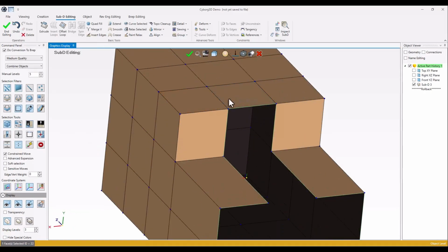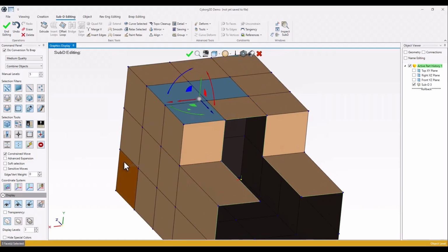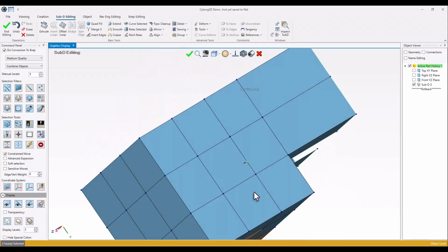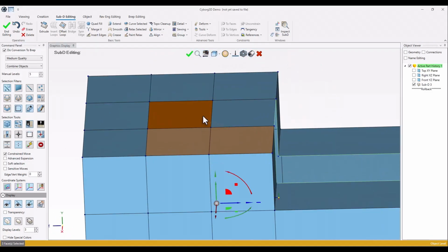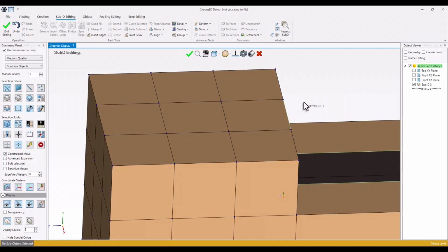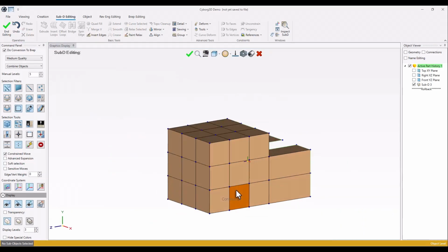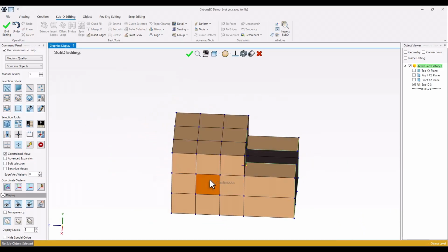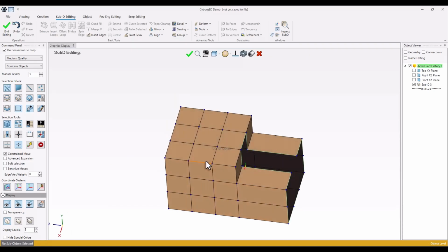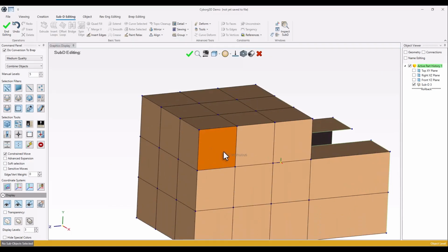And the second thing here is reverse the selection. So the inverse selection icon here, what it does, it's just inverting the faces selection you actually clicked on. Now while modeling something, we are getting to know what exactly the most things that you're gonna use.